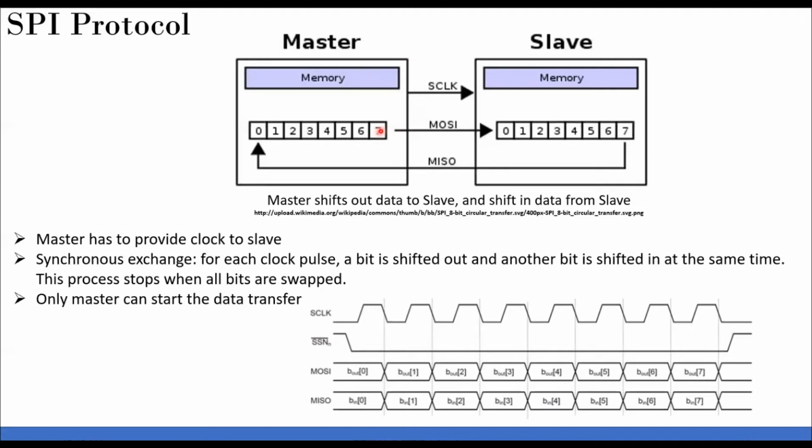Okay, so you can see this is interesting. Let's say 7-bit is simultaneously happening. The 7-bit gets transmitted at the same time from here, and everything gets shifted by 1 bit, so that this guy will come and sit in 0. By that time, everything gets shifted by 1, so that the 6th bit is at 7 and the 0th bit is at 1. So you're not losing the data. And here also 7 is transmitted, you're pushing it, so 0 will come to this 1 place, and this bit is ready to take the new bit from 7. So there is no problem of data missing or data clashing.